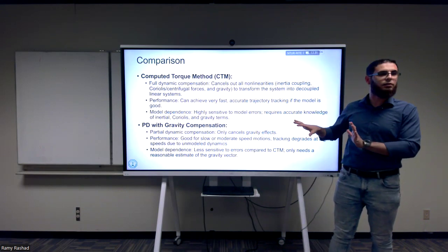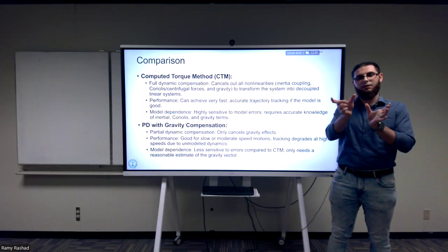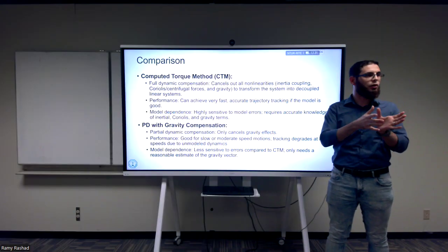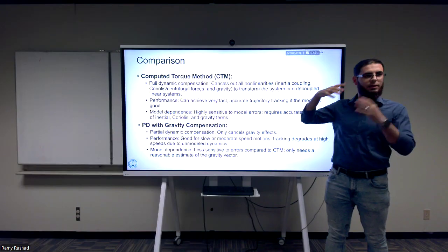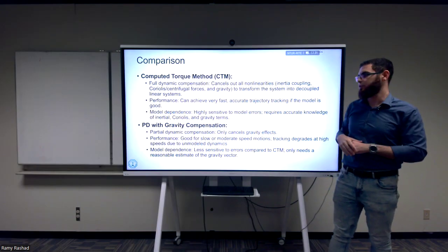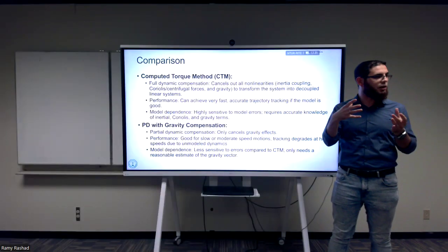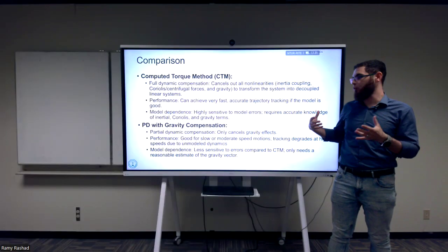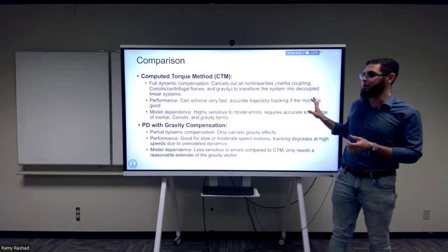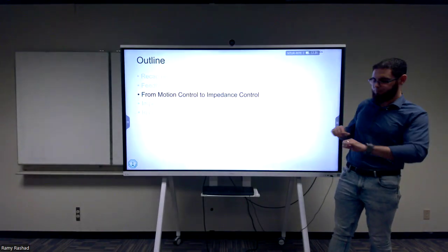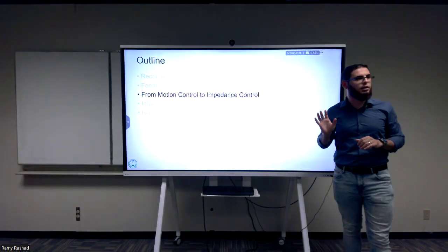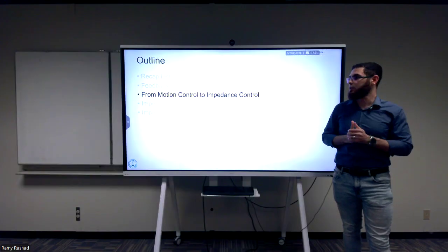So this is just a side note. Whenever you see something that has nonlinearities, let's cancel it out with the controller. You're always going to have the same problem. And this is the main idea of feedback linearization. While when we're doing the Lyapunov analysis, using the energy of the system to guide us, we canceled out only the minimum necessary stuff. So this was just a side comment, an extra part on what we discussed last time.